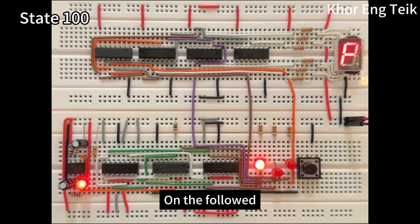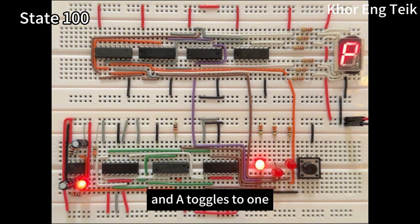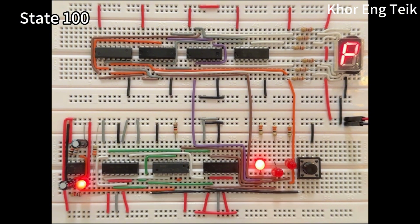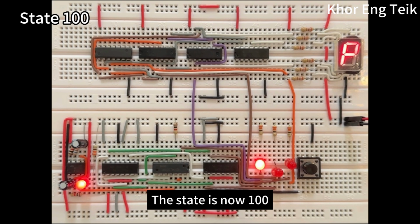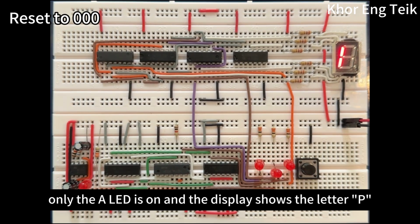On the fourth clock pulse, B and C both reset to 0 and A toggles to 1. The state is now 1, 0, 0. Only the A LED is on and the display shows the letter P.